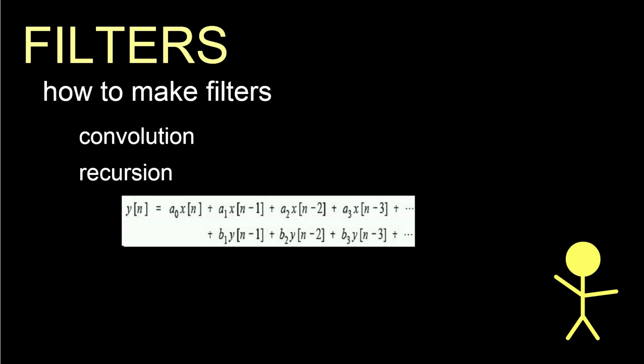There are a couple ways to make filters, but again, I will just visit two. 1. A filter can be made by convolving the input signal with the filter kernel. However, convolution is often long and arduous, so sometimes it must be avoided. The second method is recursion. We add up previous inputs and outputs, all multiplied by coefficients. The coefficients are found by using the Z-transform. How, you ask? I don't know, there is an ungodly amount of math involved.